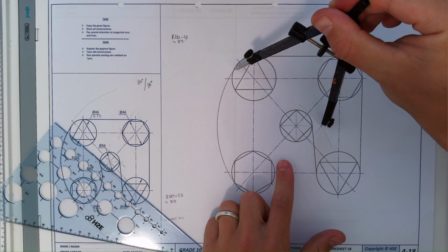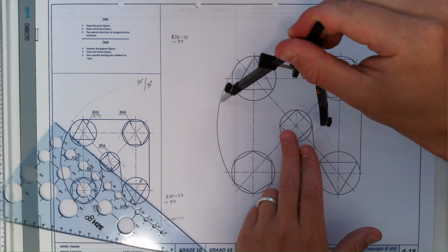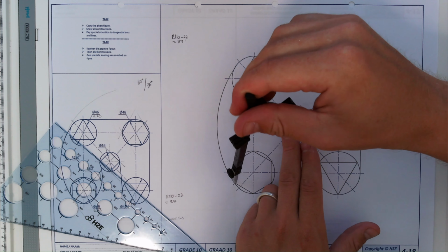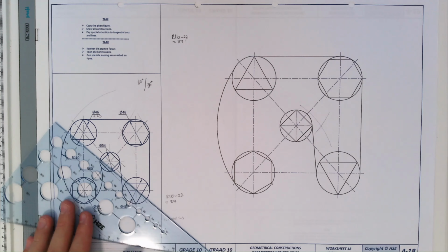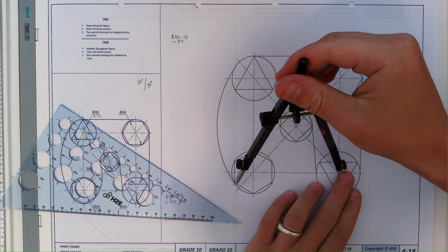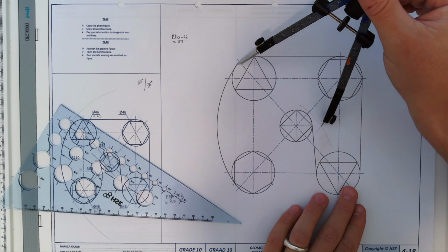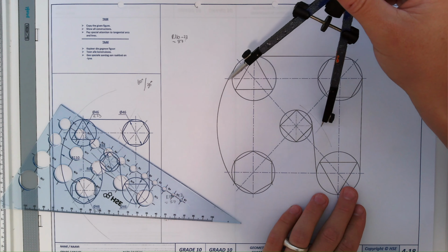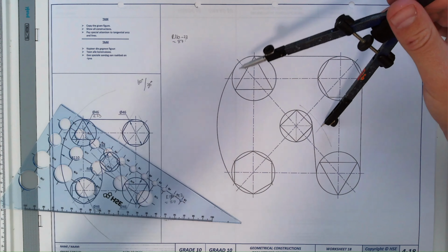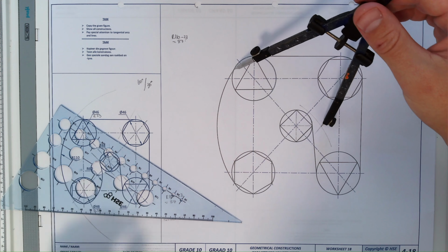So from there, nice and solid, to that one, included arc. Beautiful. When you go past those two circles, that arc should not go in the circle. Never. If it goes into the circle, you know you made a mistake and you need to recalibrate, recalculate, and redo. Double check your stuff before you make that solid arc.